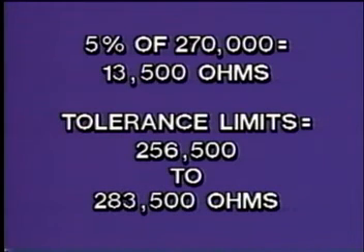Therefore, the tolerance limits are 256,500 to 283,500 ohms. The measured value of 271.3 K, or 271,300 ohms, is within these tolerance limits, indicating that the resistor is good.